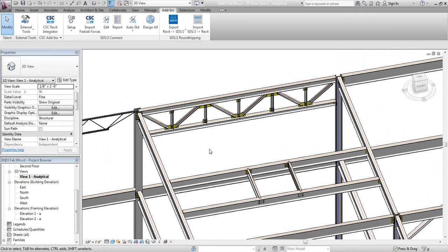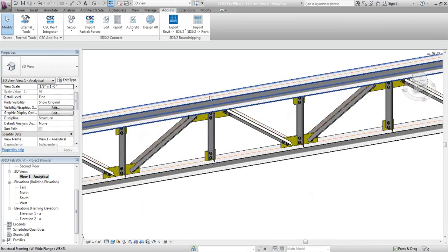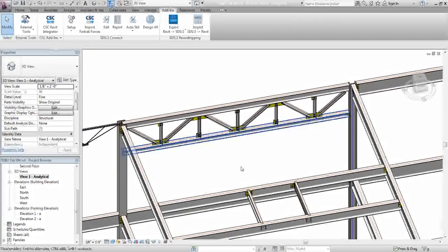If you had sloping columns also, I know that does apply to the truss really, but with sloping columns we would also be able to design the brace connections, so we should be able to do those. Again, when you're inputting those, it can be kind of picky on where the work points are, so pay attention to where you get your work points. If they're in the right spot, typically half the nominal depth of the beam, like I said, that will give the best results. So as long as we're getting that correct, we shouldn't have any problems with that.